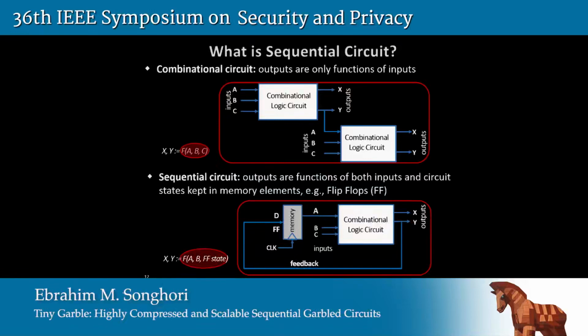All the hardware design is done in sequential circuit, not the combinational circuit. Because if we want to design a computer wholly on a combinational circuit, for a simple task, a computer would be the size of this room. It's not scalable. And also, it's not just unrolling the loop or having this memory for the loop. It can do many exciting stuff that we cannot think about with loops only. For example, shift register or a counter. If we mix them together, we cannot think about them as a loop. They're just a memory element for reusing later in the circuit.